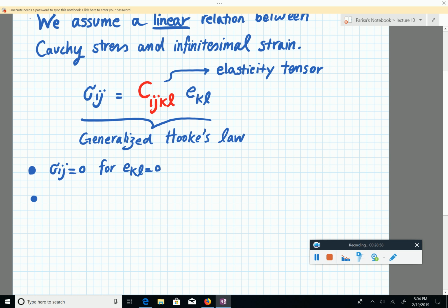So how about, for example, one example that maybe Gerald can talk to is when you look at cracks in solids, a lot of times they're like closed cracks. You really don't have any strain, but there is residual stress at the tips of those cracks. So if you have a way to measure the stress, you actually have a stress there. So it's plastic, it's not elastic. Right. So that's why this theory is not good for it. That's the whole point I'm making. Exactly. Yeah.